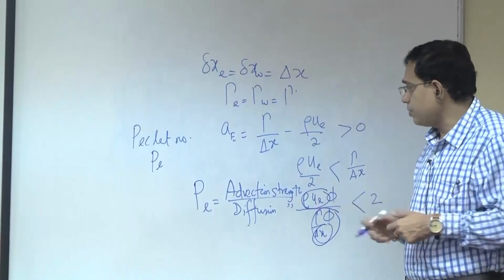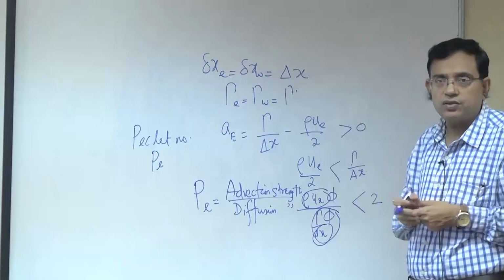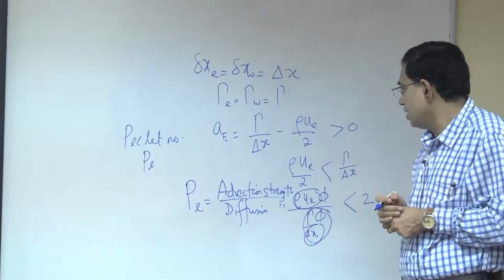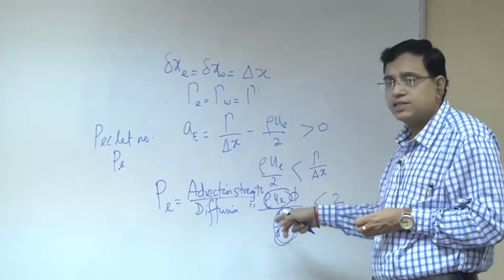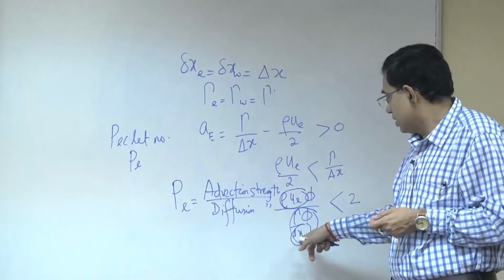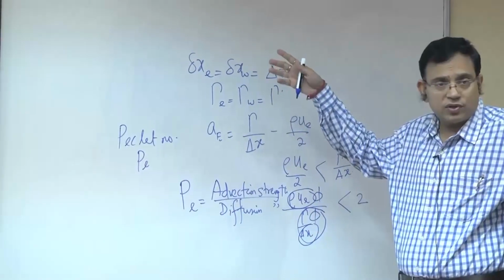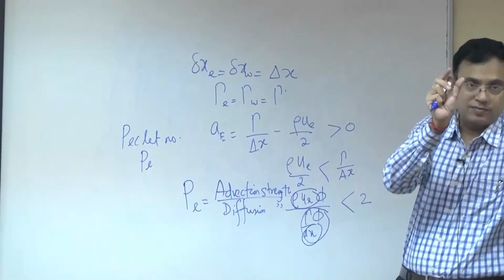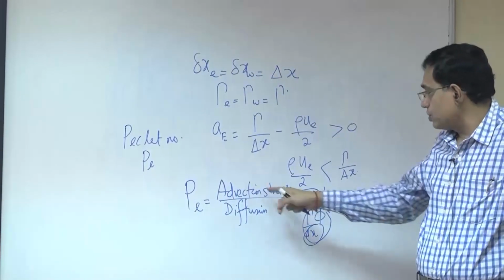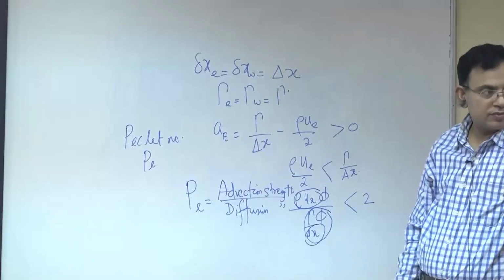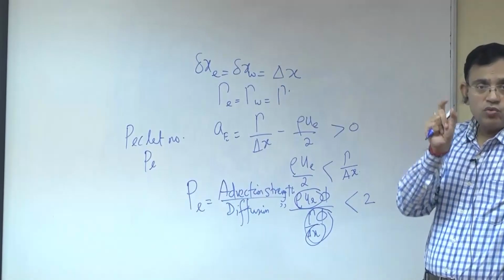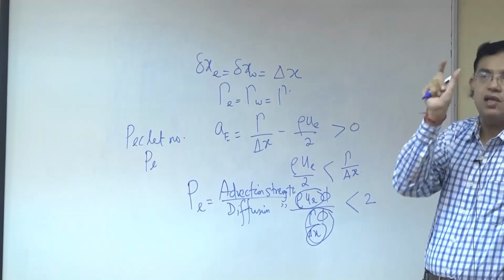So, for a physical problem, if say L is the length scale, the Peclet number will depend on the length scale L, but this is not the overall length scale of the domain, but only for the cell or control volume. So, this is called a cell Peclet number. That means Peclet number with respect to the dimension of the cell or the control volume.